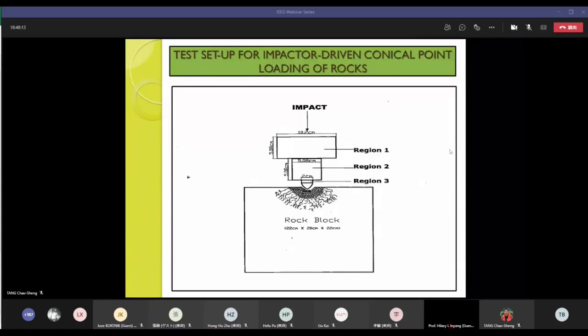Yes, as you see here, this is an illustration of the imposition of impact on a rock material. Because the stress that is imposed at the contact point is so high, material will be crushed. But beyond the crush zone, some radial fractures will result. So if I can impose this kind of load on the rock surface before the cutting bit comes around, it will significantly reduce the required cutting force.